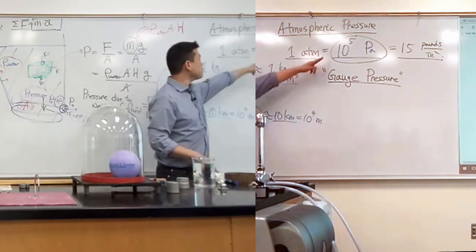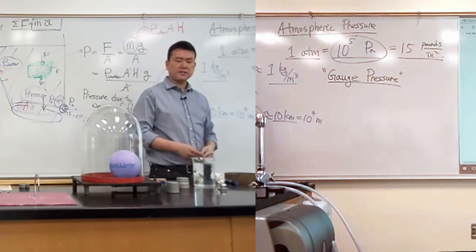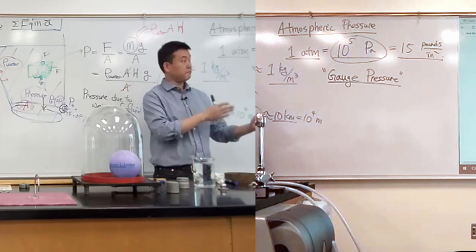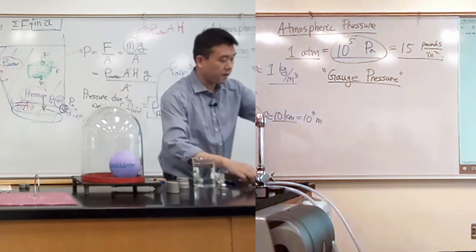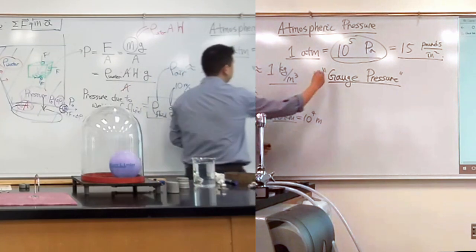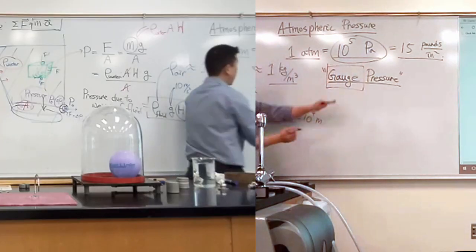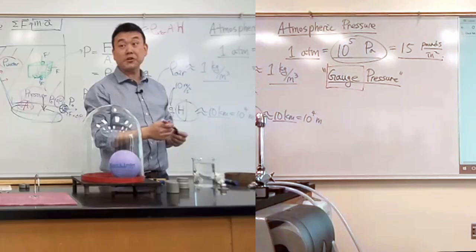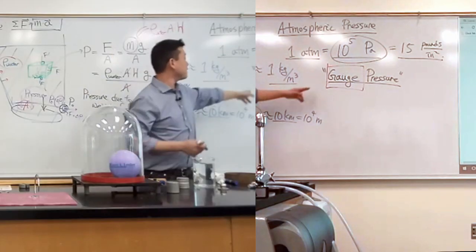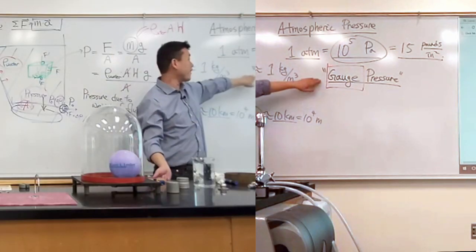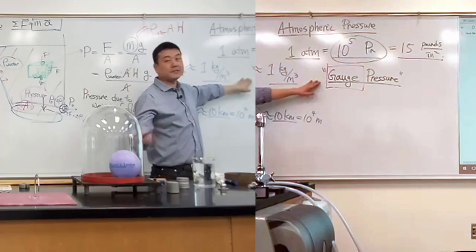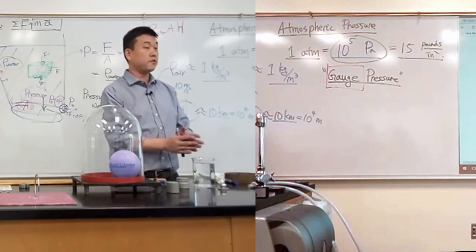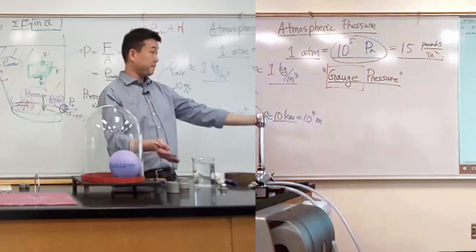So this absolute pressure, in many contexts, is actually less meaningful than stating the difference in pressure. That's where the idea of gauge pressure is useful. Gauge is actually the device that people use to measure pressure. And so this is saying the pressure you would read on a gauge. And most gauges work in a way that it measures pressure difference from outside to inside.